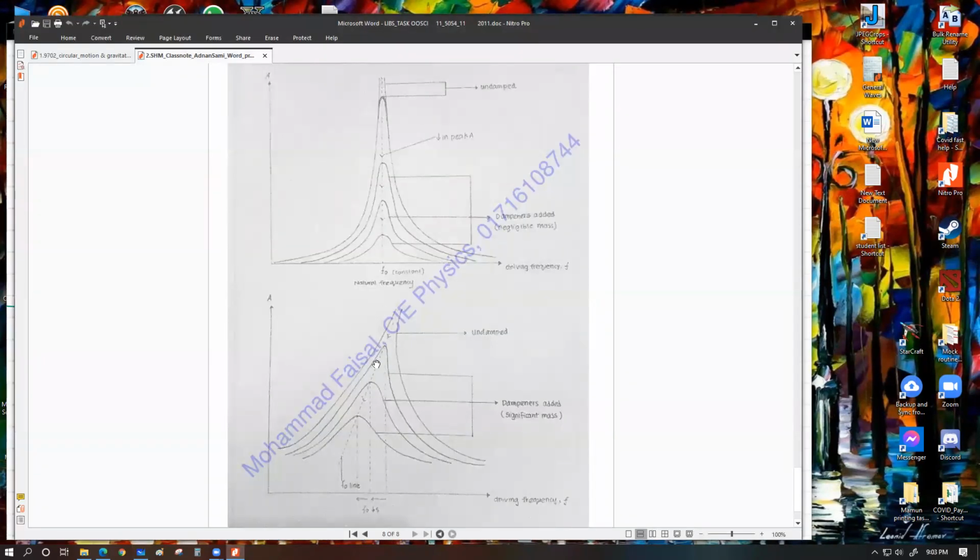What you can see over here is that the undamped oscillation is going to have the upper curve. This graph represents undamped, which means if no energy is lost, then we can have practically infinite amplitude, which is not the case for practical scenarios, because we always have some amount of damping. Even for visibly absent damping scenarios, there is always some loss of energy because of the internal collision that happens whenever an object undergoes back and forth oscillation, which is basically a portion of the elastic potential energy converting into heat energy, because layers of molecules go past each other by a small fraction and rub against each other.